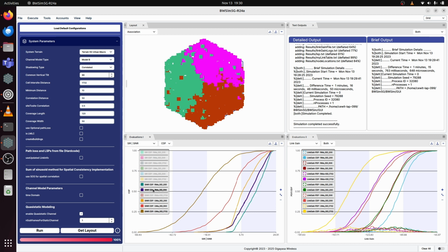So visually, one could understand that the difference in SINR behavior is more pronounced in the urban scenario than in the rural scenario. The optimal ISD in a rural scenario could be the larger one, considering the fact there isn't much pronounced difference between the larger and smaller ISD. This is because the propagation characteristics are much more favorable. The path loss is lower and the interference is less complex due to the lower building heights with abundant availability of LOS propagation scenarios.